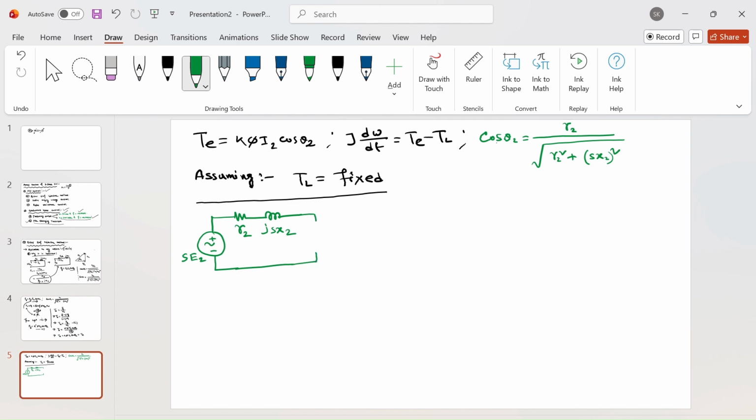Now, as of now, I am considering the voltage that I am injecting to be in phase opposition polarity, in this polarity. Let's say I am injecting this voltage from an inverter through the slip ring. Okay, why is it phase opposition? From the circuit point of view, if you move around the circuit, you will see here the polarity is minus to plus, and once you come here the polarity is plus to minus, so they are in opposition phase from the circuit point of view.